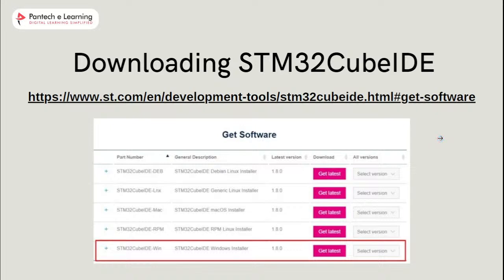Use this link to download the IDE, right? I have already told you that STM32 Cube IDE is totally for STM32 boards. STM32F4 Discovery also comes under STM32. Nucleo board also comes under STM32. So you can use any STM32 board. You can just go for this same IDE, which is STM32 Cube IDE.